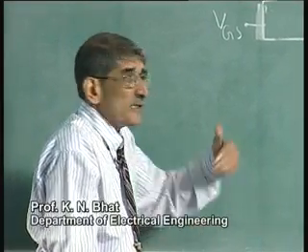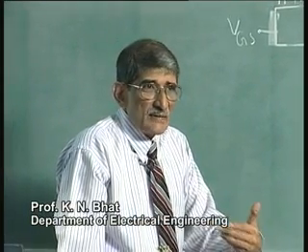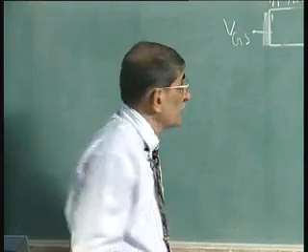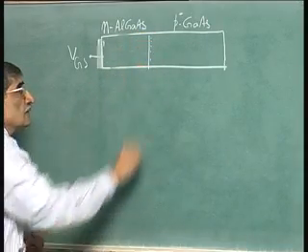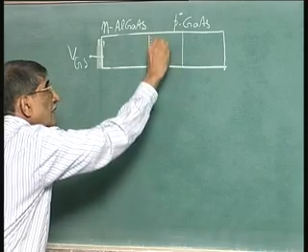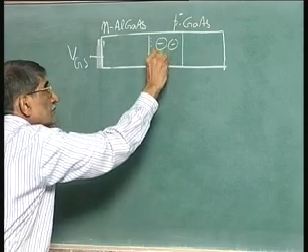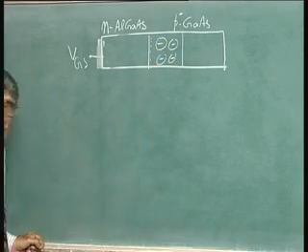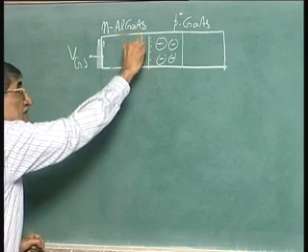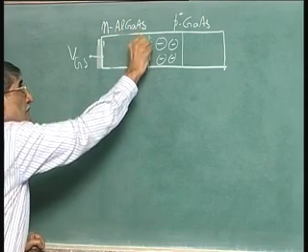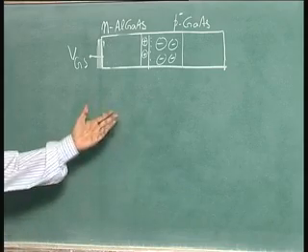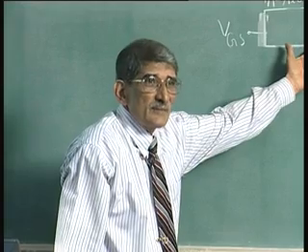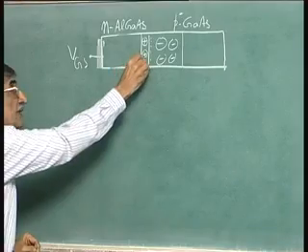The N plus layer goes all the way up to the 2-dimensional electron gas you have seen in all the diagrams. So, you have got electrons here, you have got a depletion layer here, you have got a depletion layer here, which I represented by this plus, just put 2 plus there, but the number of charges present there is large, because this is very heavily doped.